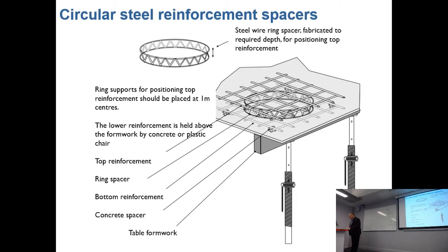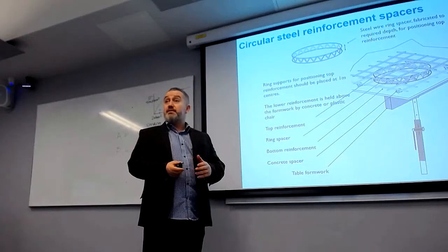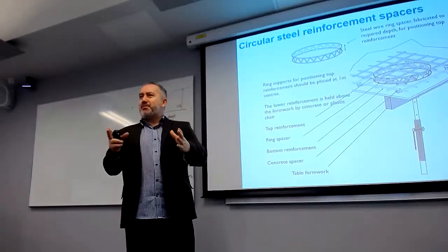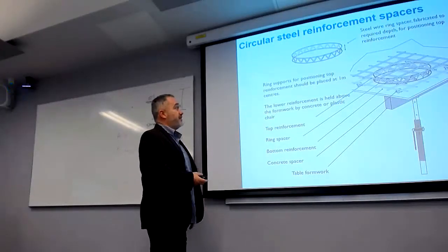The contractors will put it on because it's for their benefit. Otherwise, the concrete ends up sticking. It's like a release oil. And when you make concrete cubes, you'll use a release oil to make sure you can get the concrete cube out of the plastic mould, otherwise it's stuck.